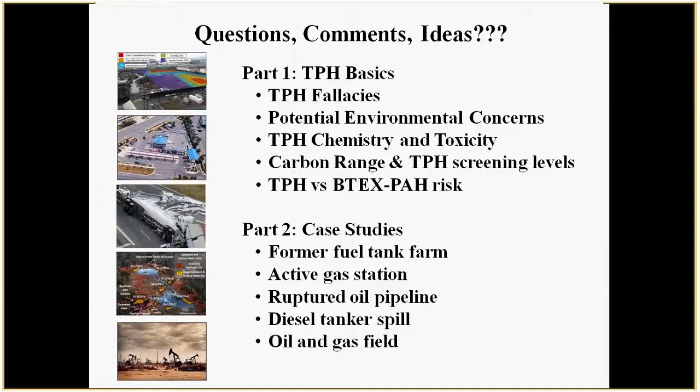It's Vicki. I do have a couple of questions in the chat box. The first one is from Angela. It says, when should we use the silica gel cleanup? So I like silica gel cleanup. I would always use it at a site where you have contaminated groundwater, just so you can document that degradation is taking place, if nothing else. And show me one site where it's not taking place. I've never seen a site where it isn't, but it's important to have both types of data.